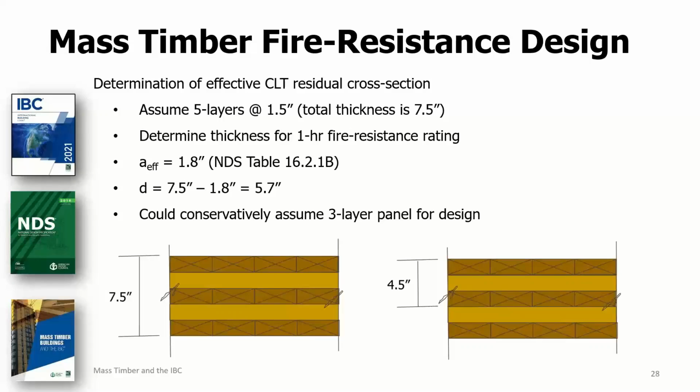However, unlike other wood members, the cross-section of CLT has distinctive orthogonally oriented layers, and this has to be accounted for in the mechanics-based design or fire design. So there is some good guidance given in TR10, especially in example 4.6 of TR10, to provide details on how this type of mechanics-based design can be handled for fire design of CLT.